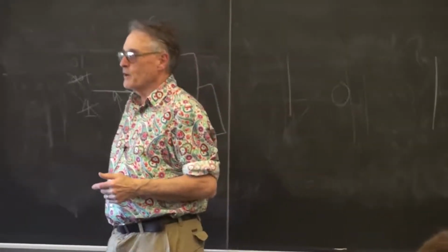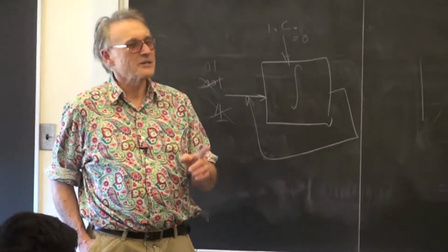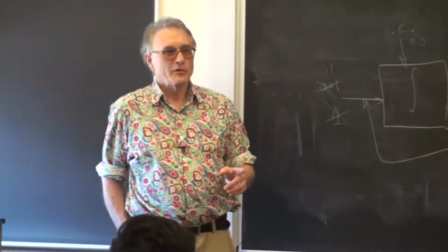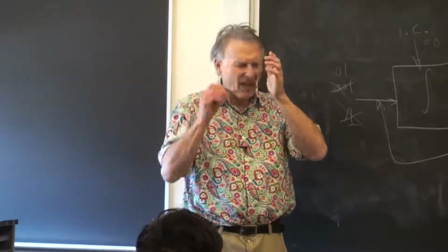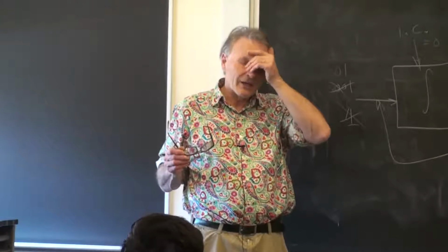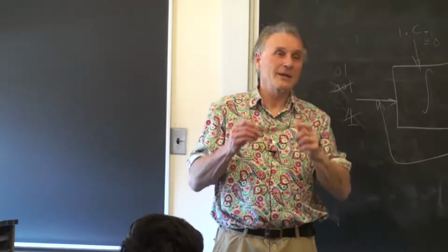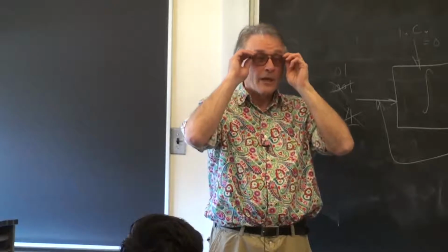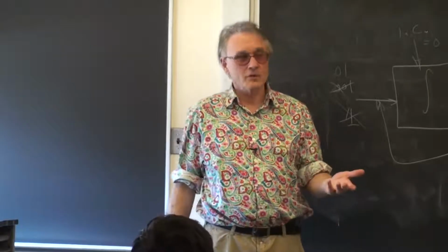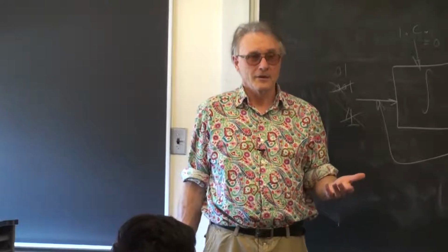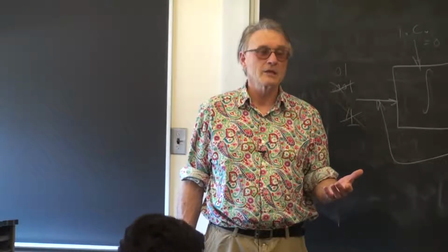I can tell you all I know in about two sentences. I haven't tried it yet on this architecture. There is certainly an interrupt line, and the HPS will recognize an interrupt, but you have to modify the kernel to make that work. In the interests of trying to get the course running, I didn't have time to blow the system away and start over a couple of times.